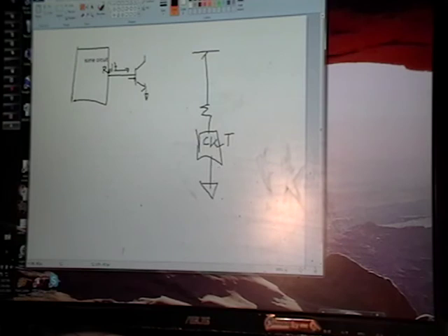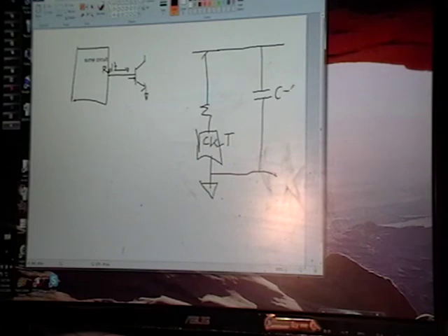And this circuit was really noisy, and it was putting noise on the supply and ground. What you can do is, so these are 2 wires. Anywhere there's a wire with DC on it, if you put a bypass capacitor on it, and the closer it is to infinity, which you know you can't get, but the larger it is, the quieter VDD and ground will be.